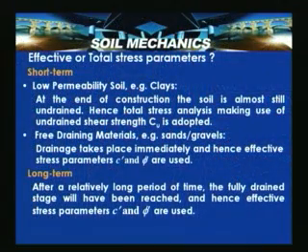Now, having discussed this, if you remember, there are two stress parameters which come into the picture. One is the short term stress parameter, the other one is the long term stress parameter. In soil mechanics, for long term conditions they are effective stress parameters, and for short term conditions they are total stress parameters. When to adopt these depends upon the short term and long term stability conditions.